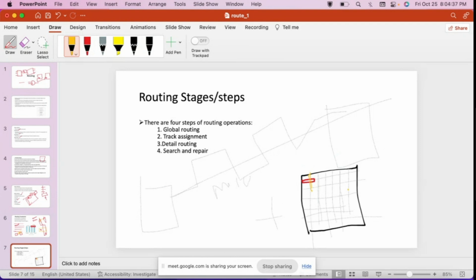You have to give the way to route, and in specific locations or in critical cells, you can say this cell has to route. You can have some conditions, like don't use, don't touch. You can define for some cells that they have to be routed only in M1, M2, M3, so they should not go to a higher layer. That also you can constrain. So these are routing constraints in your design.